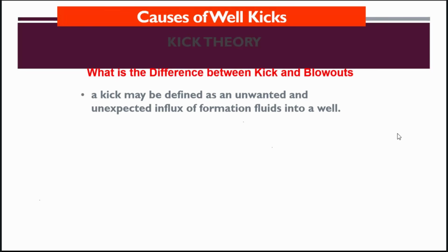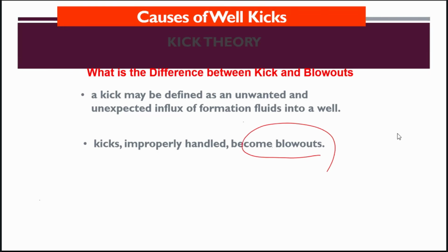So the kick and blowout difference we have already seen. A kick is unwanted or unexpected fluid which we get from the formation into our well. But it can be handled. It can be circulated out safely. But if kicks are unable to be circulated out safely, or if they are not managed properly, it can quickly become a blowout.